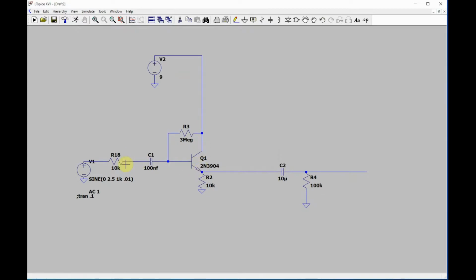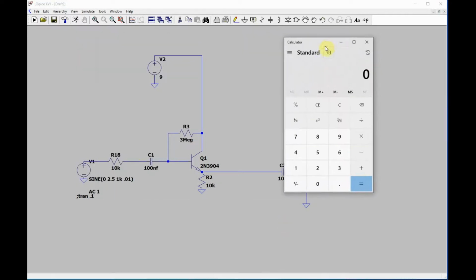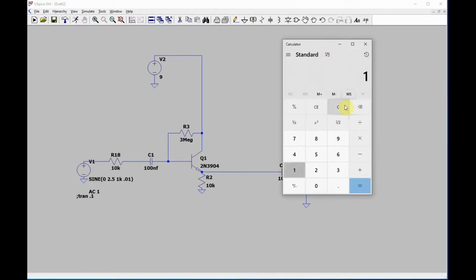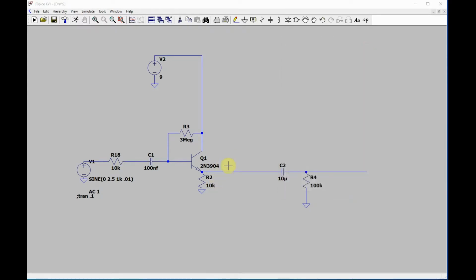And so what you do is you take the impedance looking backwards, you divide by the HFE. So in this case, it's going to end up being like 10,000 divided by say 300, for example. So that's like 33 ohms, very low. Now it's not low enough to drive headphones, because headphones may be like 8 ohms, right? But for a lot of circuits, it's considered low impedance.